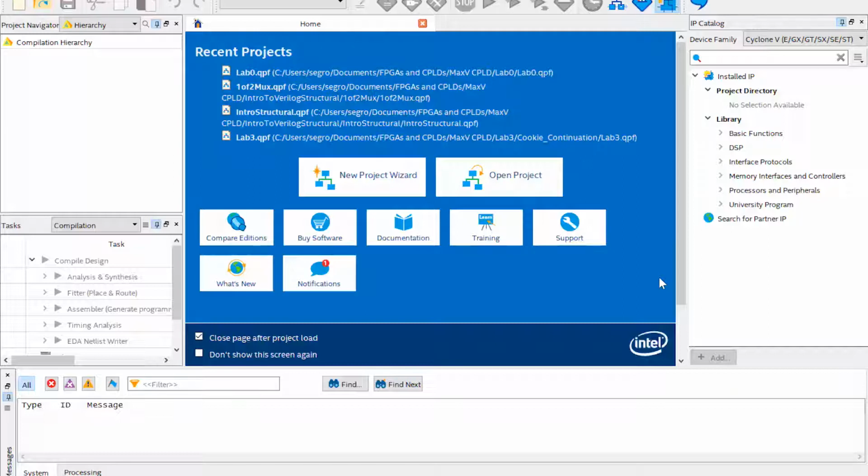Okay, so that's pretty much pages 1 and 2. You can read through the overview of the hardware itself. I think that's self-explanatory. I just want to focus on actually using it. One of the things I do want to reiterate is that you want to use 3.3 volts only. It does have a 5 volt to 3.3 volt regulator on there, but I might change that for later editions because I think it might cause more problems than anything else.